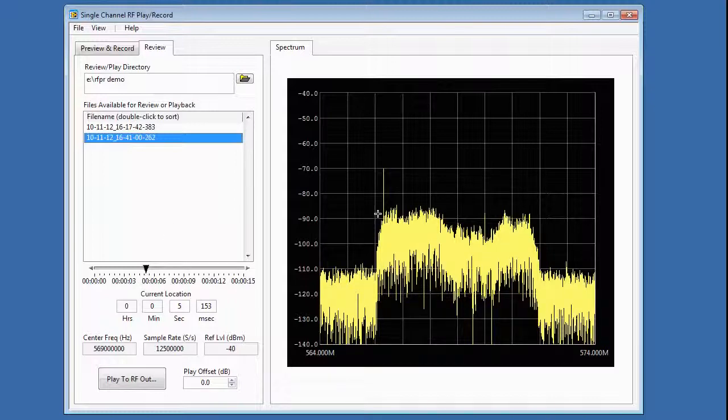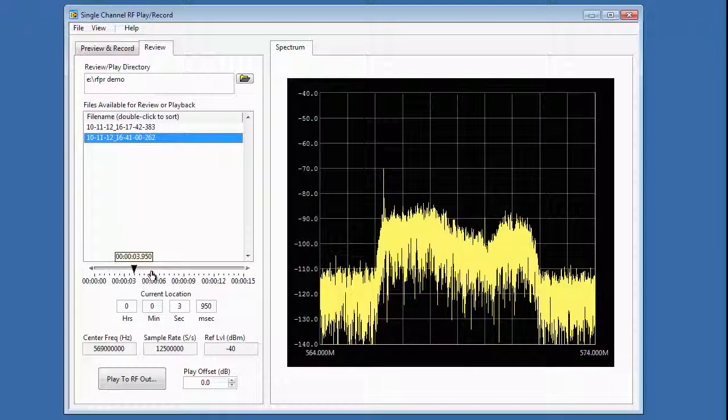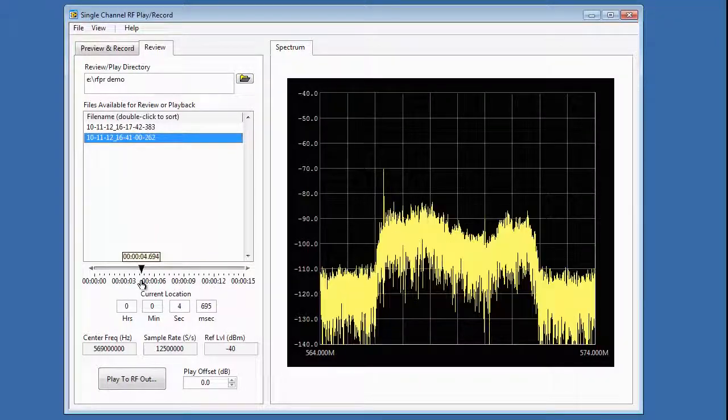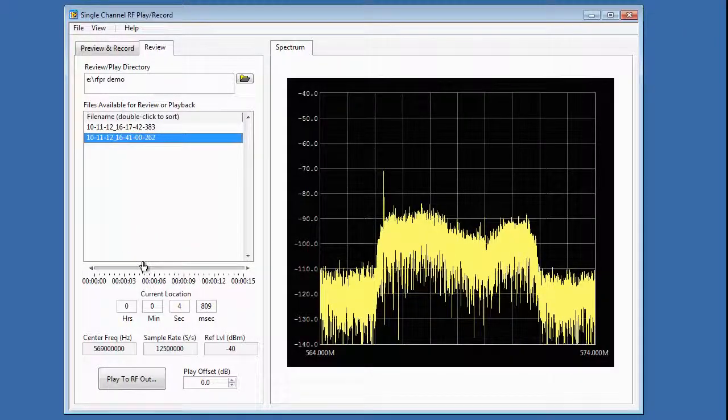Okay, so that looks like an interesting signal. I think it probably would be a little challenging for a real-world television to decode that. So let's try it out. I've connected a TV, digital TV, to the SMA output port of the National Instruments Vector Signal Generator, and as soon as I hit play down here, this RF data stream will play through the RF Vector Signal Generator into the television, and we will find out if the TV can decode that multipath impaired signal.